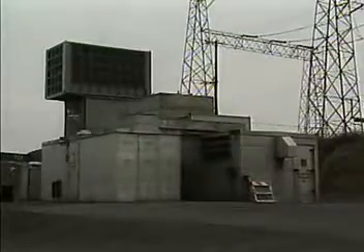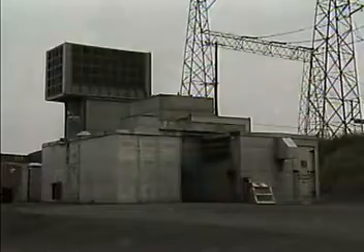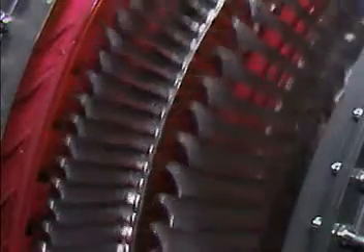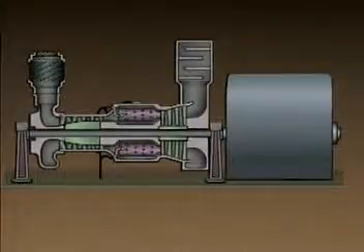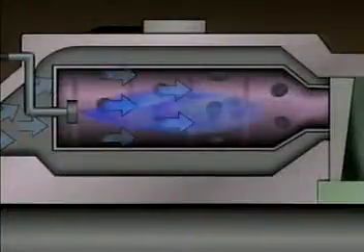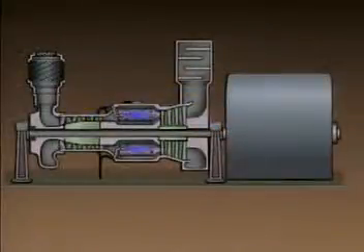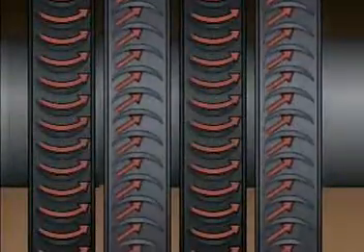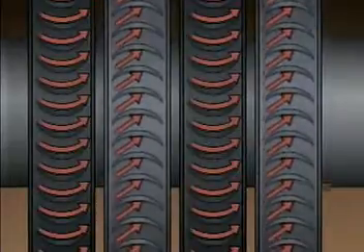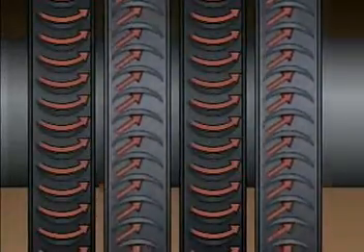For example, some generators are driven by gas turbines. Like steam turbines, gas turbines take energy from a fluid moving through blades. Gas turbines use hot combustion gas that's produced by burning a mixture of fuel and air. In fact, gas turbines are sometimes called combustion turbines. As the fuel and air mixture is ignited and burned, the hot gas expands and flows rapidly through the turbine blades. The thermal energy in the hot gas is converted to mechanical energy, which causes the turbine shaft to rotate.